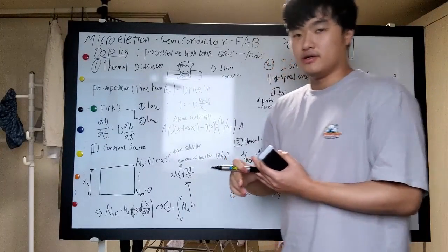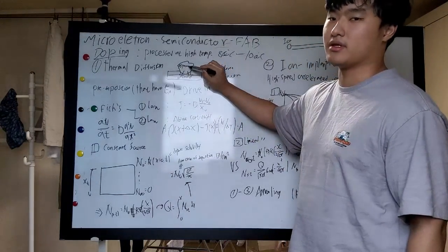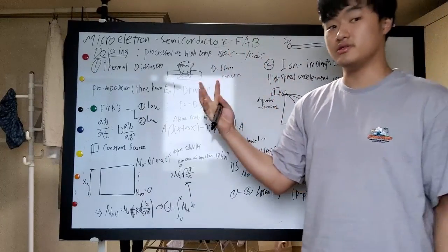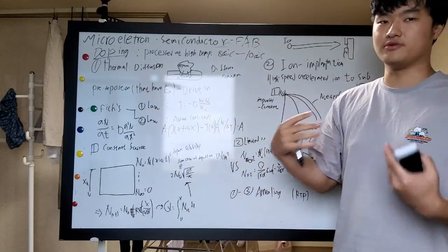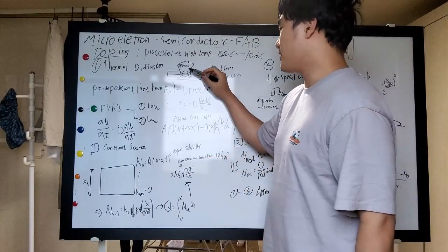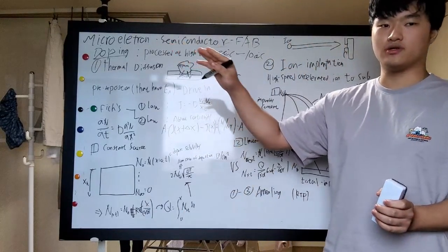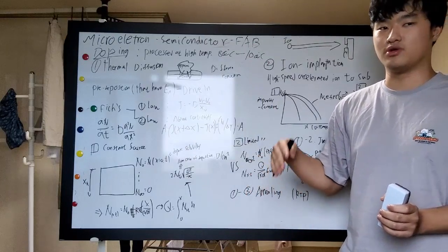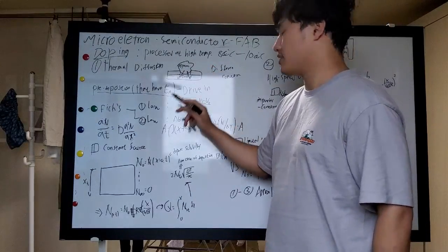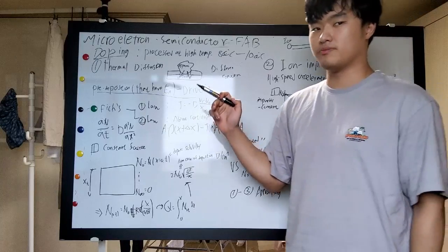So first, place the dopant material on the surface, and secondly, with pressure from gas or heat, the dopant will be diffused by the difference of concentration of each material. And we know that at higher temperature, the materials will react more actively. So first, pre-diffusion on the surface, and then driving, it means being doping mode.